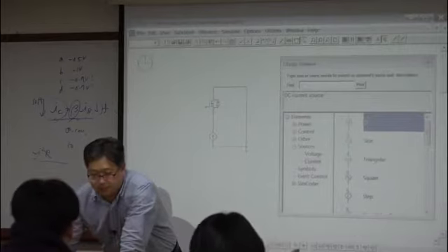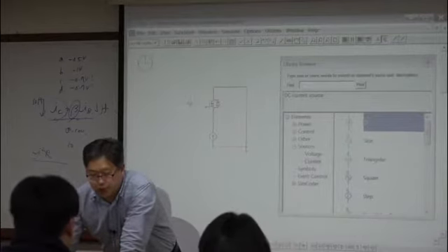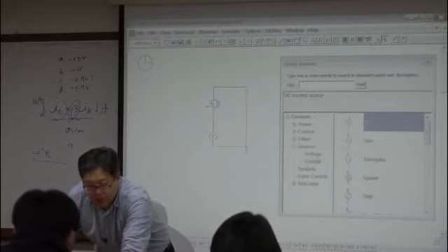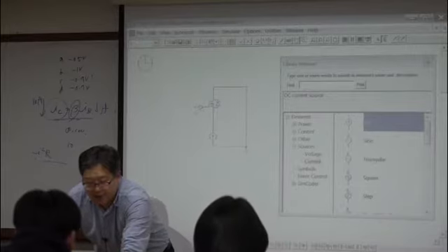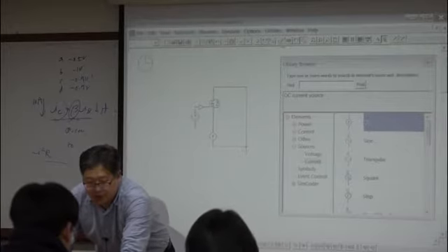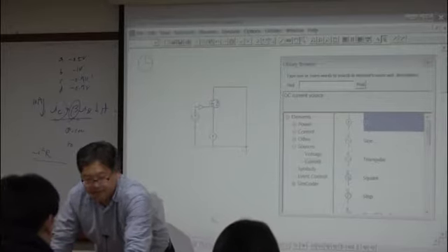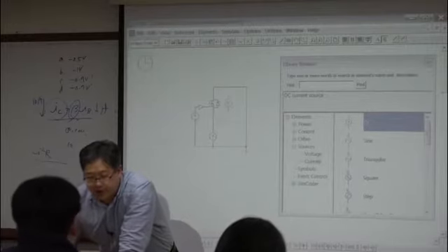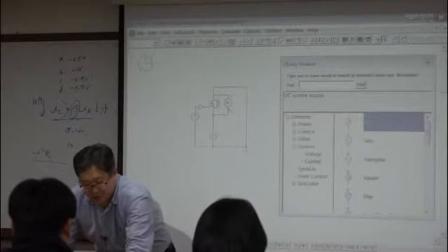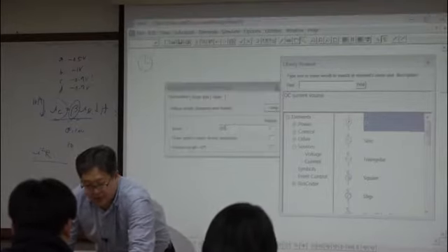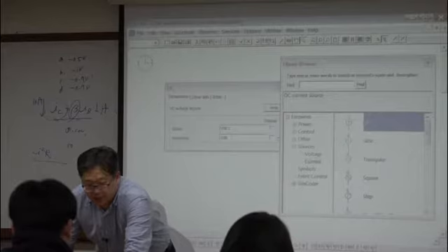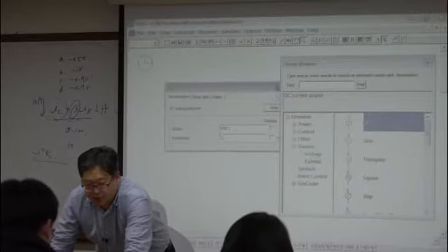And to control the gate, you should have the on-off switch controller. It looks like a simple triangle, and you can add a voltage source here like this. And let's measure the drain to source voltage like this. Then go to here, that is VDS1, and you can display it like here, and simply make amplitude to be 1.